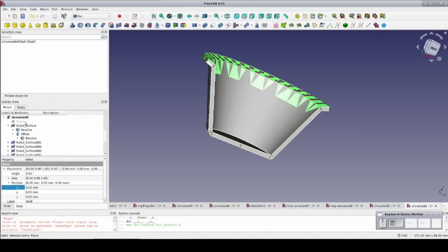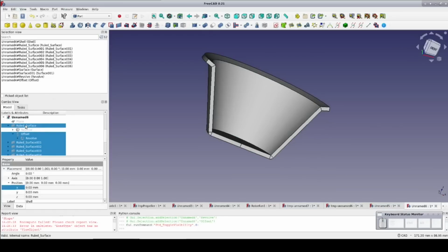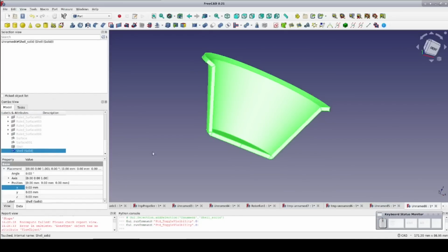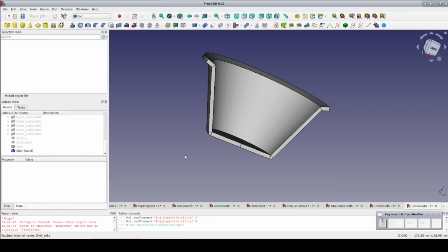At some point, the Curves workbench may become a full part of FreeCAD, which will make the Fill Boundary Edges tool available to the Part workbench. Maybe it'll even be placed in the Part workbench. But once it is, it'll be available to the Fill option of the Offset tool, and so it would be able to complete the operation for itself as we would expect.